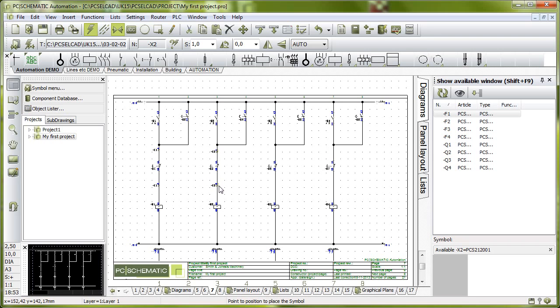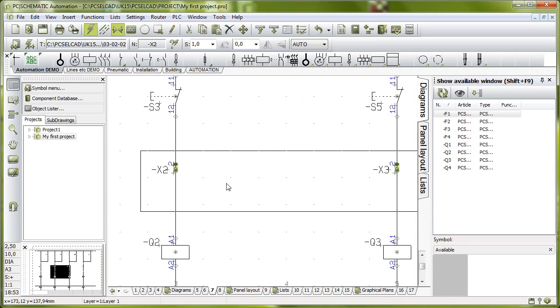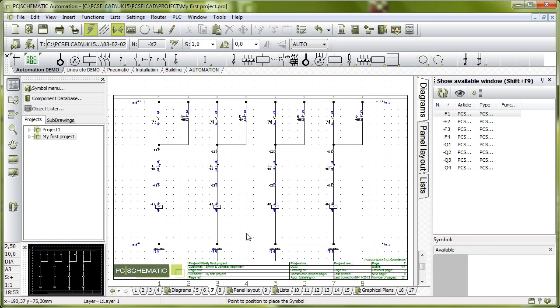control circuit. If I want to do this for the page here, I could copy my terminals and add them here, and again add them here, because all those terminals here would need to turn upside down, and in this one I can pin swap here. Now the right click menu is not that big. Pin swap, and that means that you see they turned upside down. So now my terminals are okay.